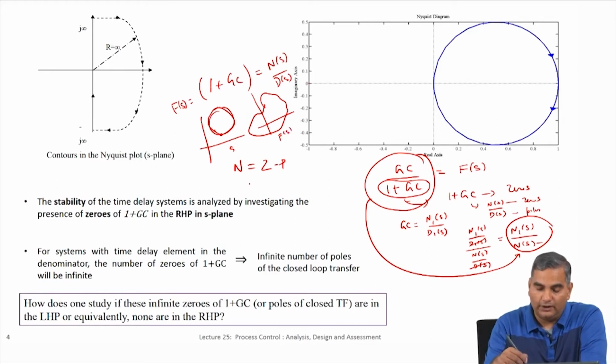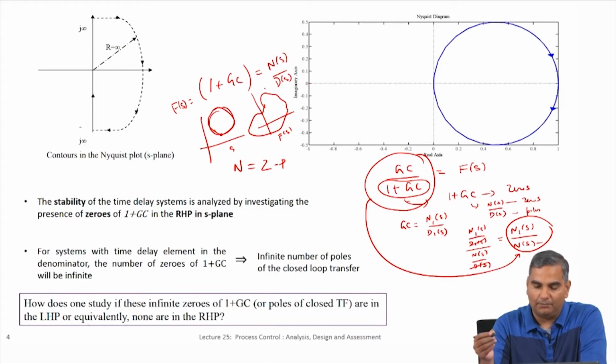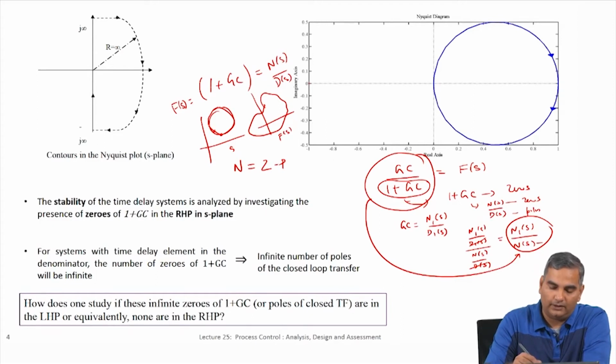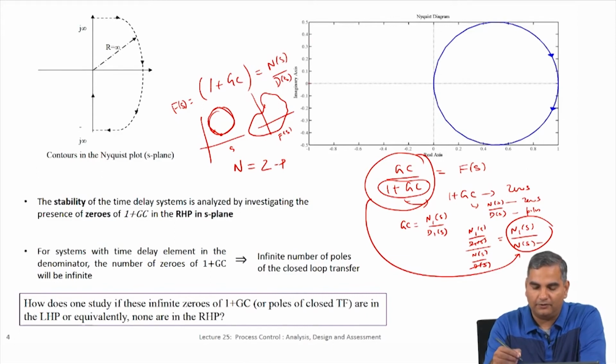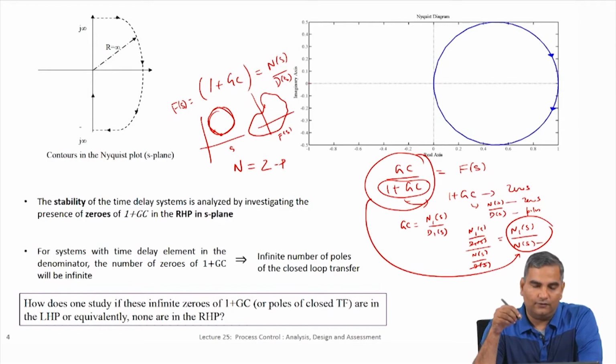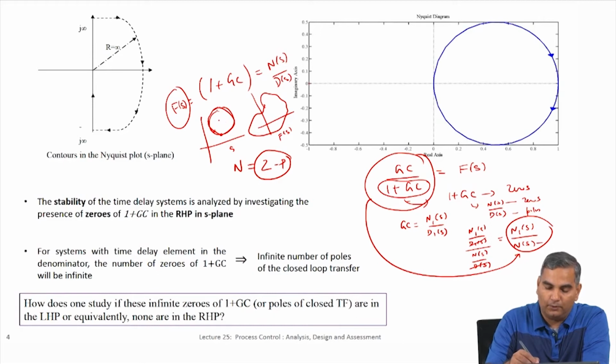Remember this, you do not need to know the zeros and poles, because it does not even have to be in the root resolved form. I have a numerator polynomial, I have a denominator polynomial. Conceptually what I am doing is I am taking every point here and finding a corresponding f of s, and simply substituting it. So once I find the corresponding f of s, I will get a contour here. Okay. So it can be just a polynomial form, not even root resolved form. Now without finding the roots, what I can tell you is, within this contour for this f of s, what number of poles and zeros there are in terms of a difference. So I can tell you the Z minus P. So how many zeros minus poles are there inside the contour.